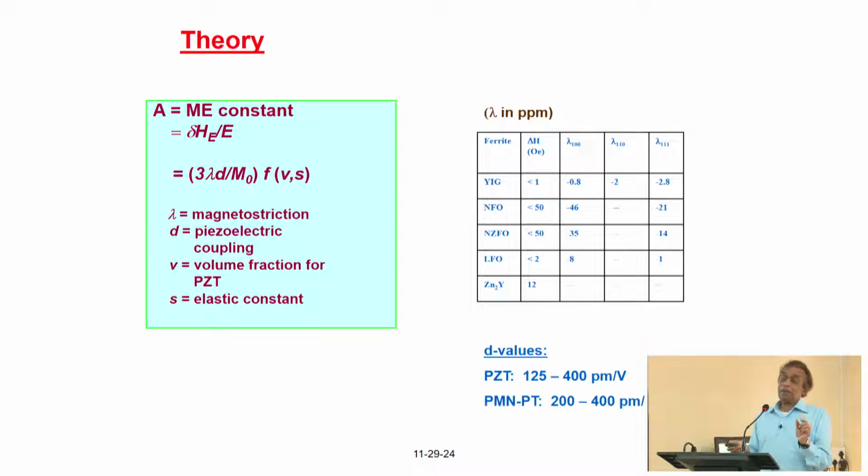That is a key parameter, because when you tune a device, the question is what is the tuning range compared to the line width. If I can tune the device by several line widths, that is what we prefer. That is where the advantage of using YIG comes in. Nickel ferrite and lithium ferrite have a slightly higher line width compared to yttrium iron garnet.